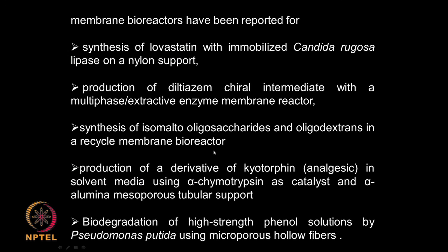They have been used in a large number of systems: synthesis of lovastatin with Candida rugosa, production of diltiazem chiral intermediate using a multiphase extractive enzyme membrane reactor, synthesis of isomalto-oligosaccharides using a recycled membrane bioreactor, production of a derivative of an analgesic using an alpha-alumina tubular support and alpha-chymotrypsin, and biodegradation of high strength phenol solutions using Pseudomonas putida trapped in microporous hollow fiber.